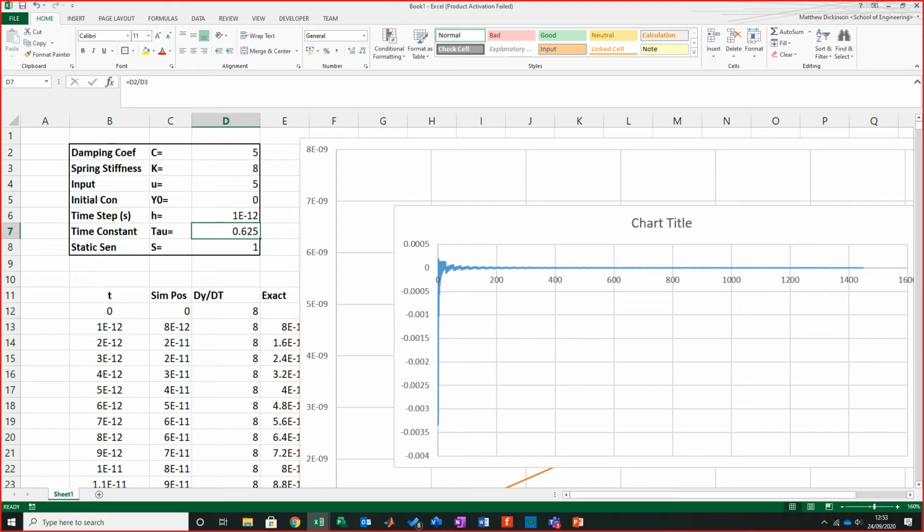Each system that you're building... when we get into meshing a little bit more, I'm going to show you how the stiffness matrices work and how they're simplified as it goes through. If this simplification process is too big, it doesn't know where it's simplifying, the equation becomes unstable, and this is the type of response that we get.